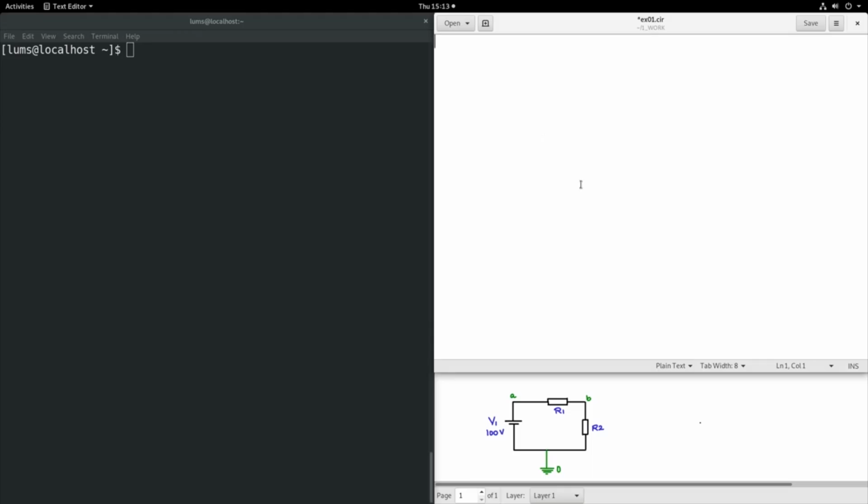Before starting to write the .cir file for Spice simulation, download the manual of NgSpice and read through it. The first line is always a comment line. It's a title line. You write the title, let's say a simple attenuator circuit. The line where the star is the first character, anything followed by the star, is a comment line.